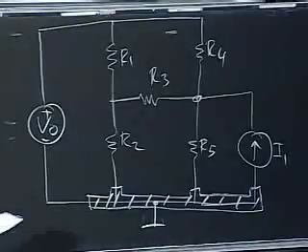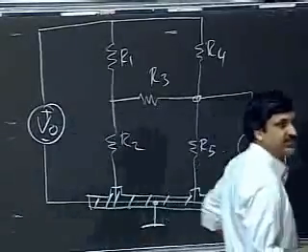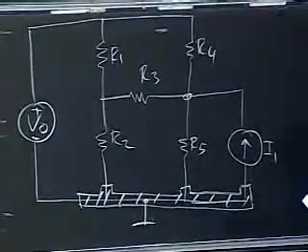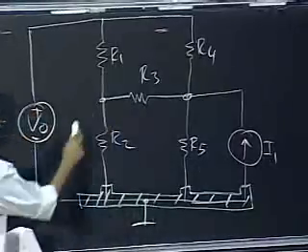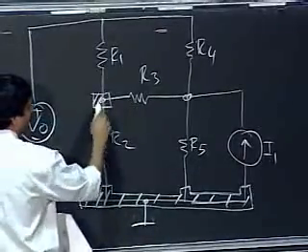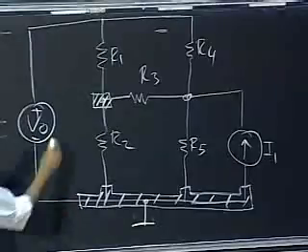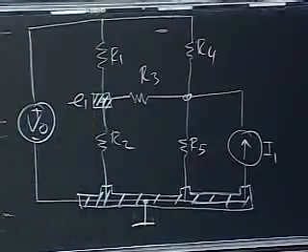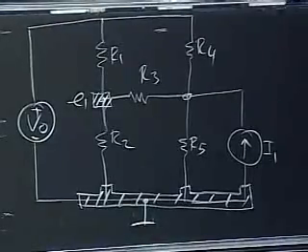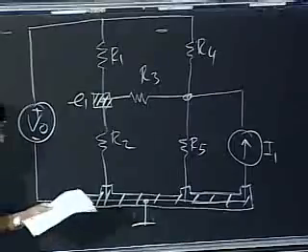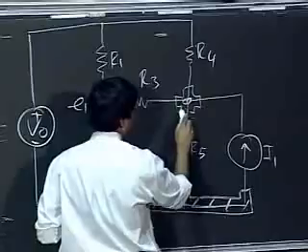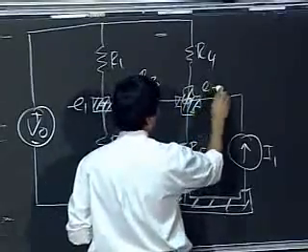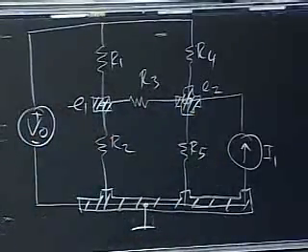Second step, I'll label the voltages of the other branches with respect to the ground node. Okay, so what I'll do is have this node here. So I'm going to label that voltage E1. These are my unknowns. Remember, node method, because my node voltages are my unknowns. So I label this as E1. I label this one as my unknown voltage E2.